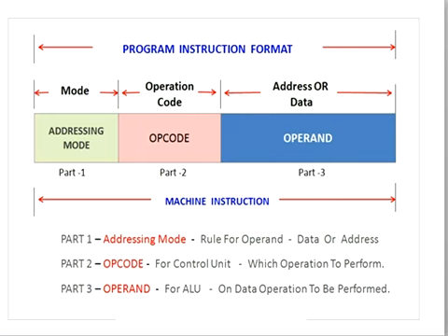An instruction will be read from memory. That instruction is stored inside the instruction register. We already know the instruction register. The size of the instruction register is 16 bits, from 0 to 15. Bits 0 to 11, the first 12 bits, are used to store the address of the operands. Bits 12 to 14 denote the opcode, and the 15th bit specifies the direct or indirect bit.